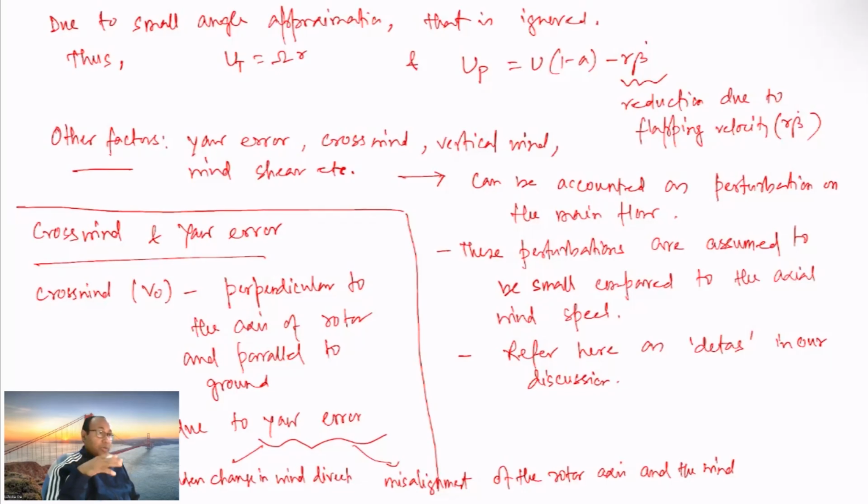And so what happens is that this crosswind tends to increase tangential velocity at the advancing blade and decrease it at the retreating blade. So we have already defined the crosswind from left to right in one of the earlier figures or diagrams. So considering that, we would take into account this effect. So we'll derive that in the next session.